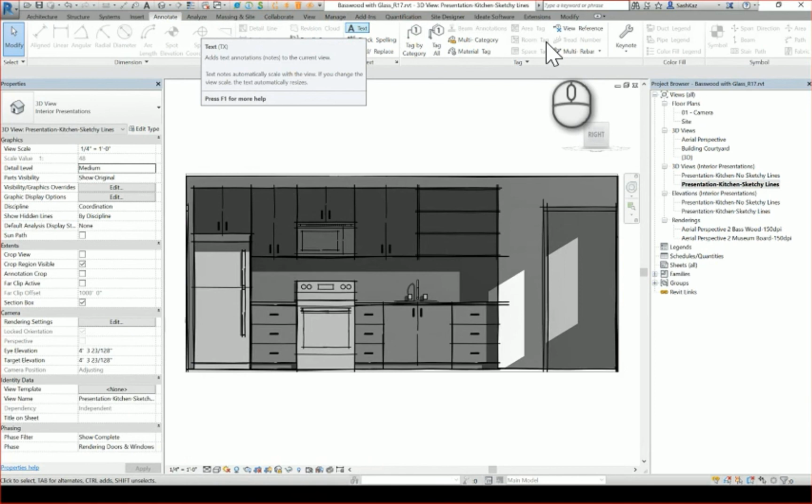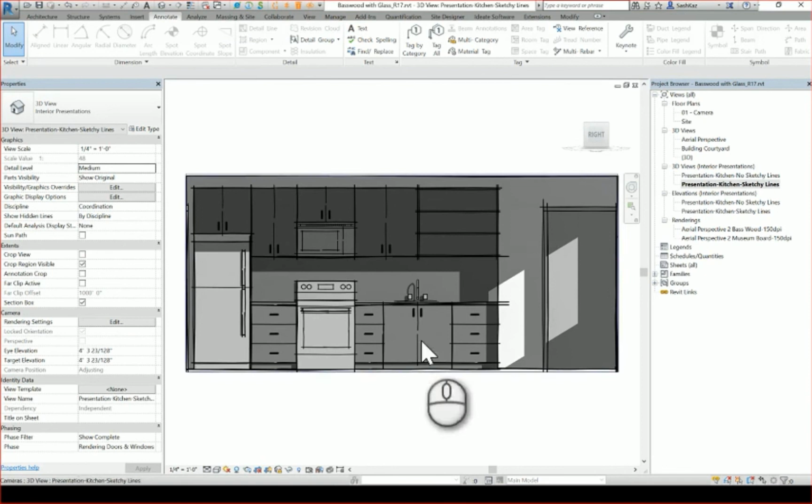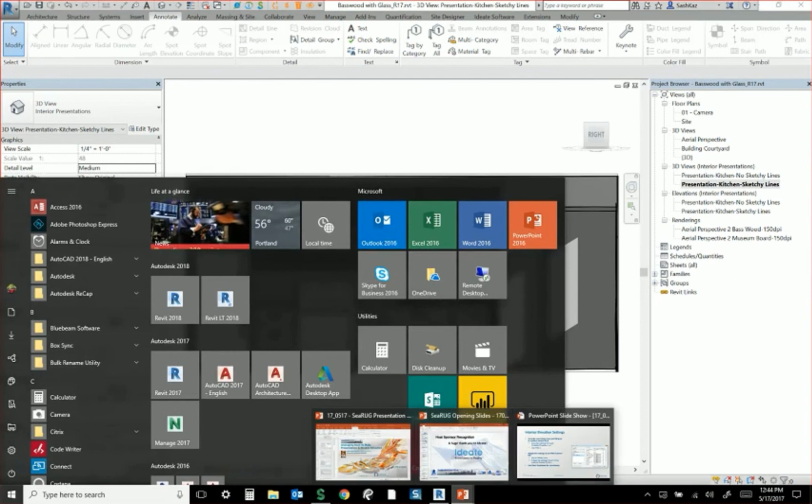Before, I don't know how many of you have done this, you go do an isometric detail, and you're like, I just want to orbit it just a little bit more, and all of a sudden the tags fly, or not the tags, but the text fly off. Well, save orientation and lock view, that's right here, this house with a padlock. That one will prevent you from making that mistake, which I've made millions of times. So you can still do some basic documentation in this view if you want to. Great question. Cool. All right, I'm going to come back over here.